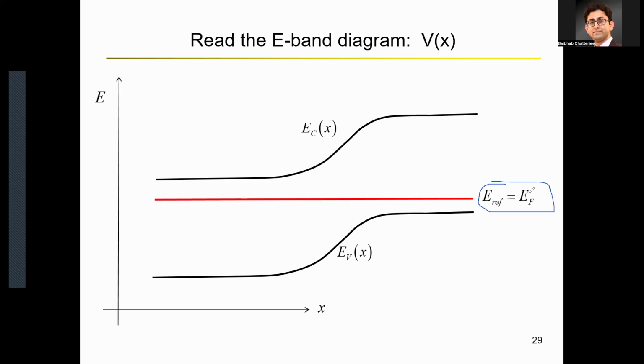So it's an average energy that an electron has in the entire structure. Why is this important? Because this tells us, be it a p-type semiconductor or an n-type semiconductor or a p-n junction diode or a MOSFET, there would always be an average. If you take all the energies of the electrons, you'll just get an average number. And the Fermi energy gives you that average number.